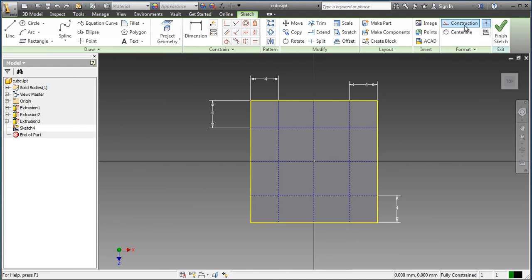What I want to do now is go back to undo. I'm going to click on my construction line to deselect it, then click on the circle tool. Now locate the centre, draw out, type 3, press enter, and I've got my circle with a full line and it's already dimensioned to 3mm, so I don't have to dimension it.